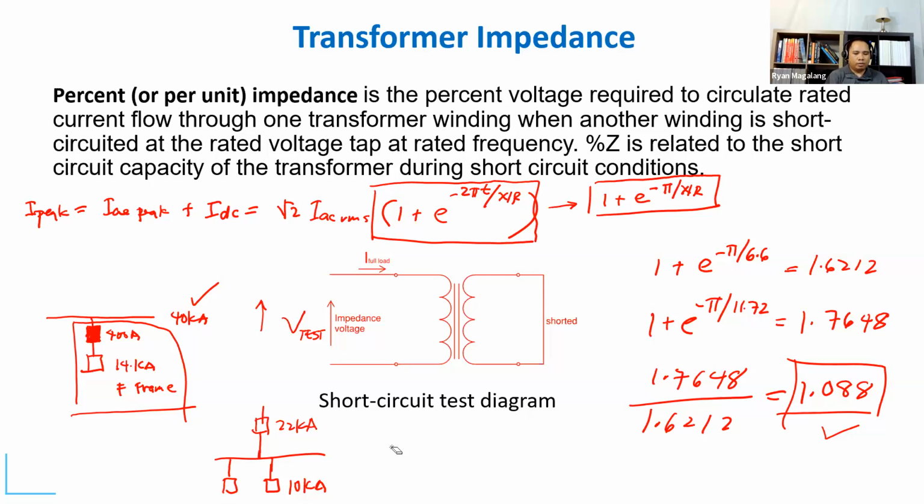They have to be coordinated such that the main breaker is able to protect the branches. But personally, I would select the fully rated. When we say fully rated, all of the breakers are of the same rating, including the panel.